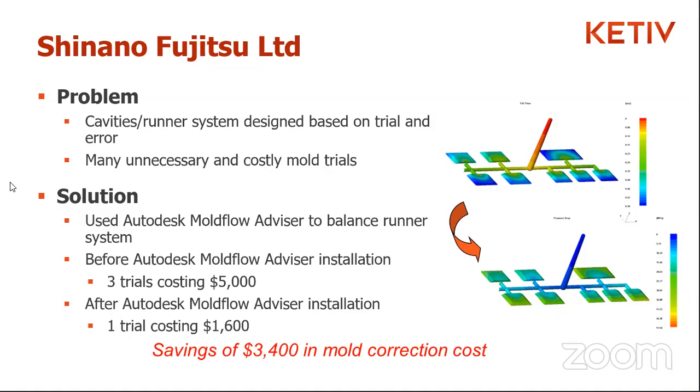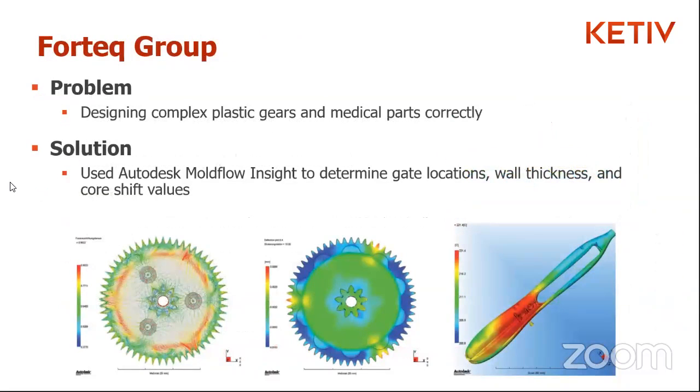And if you're not filling things at the same time, basically the bottom line is if you're not delivering the same melt, temperature, pressures, shear rates, or stress velocities, you're going to get different physical properties and cosmetics, which is always this tug of war. So balancing it here, you can see saves a good amount of money